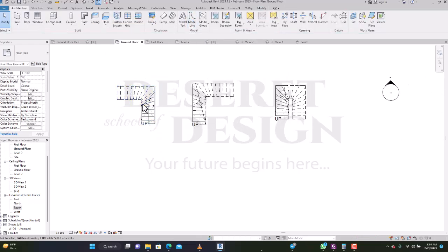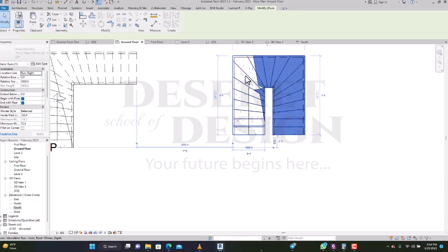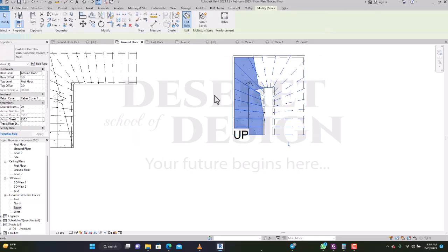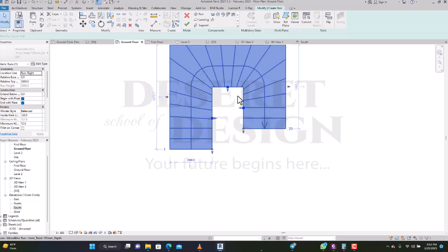Now look at something. You see the way the U shape and the space here is small. Maybe in a situation where that gap is big, the place you are placing the U shape is supposed to be stretched. Do you get it? So you select your stair, edit the stair. Now, this thing comes with a drag pull. If I open up this, you see what is happening? It's reducing.